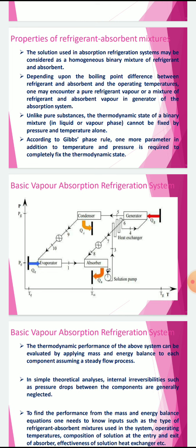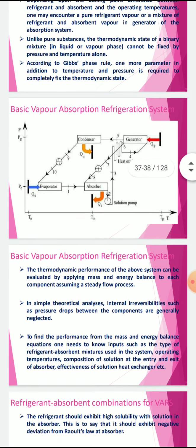That strong solution is pumped to the generator, and in between we have a heat exchanger in order to increase efficiency, effectively using thermal energy. Anyhow, we need to heat the pumped solution, so we pass it through the tubes of the heat exchanger carrying the solution coming from the generator towards the absorber. So this is the basic thing that is happening.